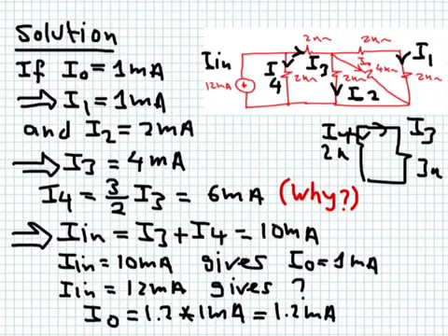Okay, so now we know, and of course you are welcome to repeat these same steps using the way we did in the lecture. Combine all the three, combine this one, get one equivalent resistance, use current division. You will see that the current flowing here is equal to 4.8 milliampere. You get 1.2 milliampere here, 1.2 milliampere here, and 2.4 milliampere here. So I didn't make this verification.